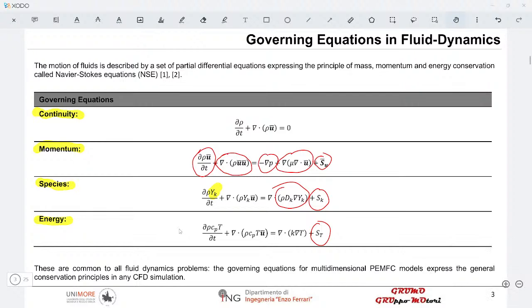Okay, so this in a nutshell is how we use the generic model of a transport equation that you see here. It can be declined basically for any variable of interest for our CFD problem. And this type of model, the transport equation model, has been used and adapted to also completely different CFD problems, like, for instance, combustion modeling.